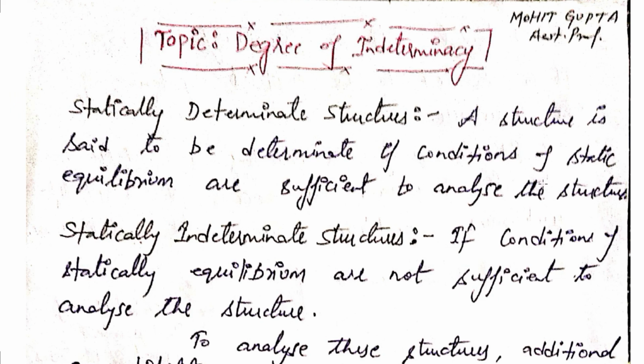We know that in determinate structures, bending moment and shear force are independent of properties of material and cross-sectional area. We also know that in statically determinate structures, no stresses are induced due to temperature changes, and also no stresses are induced due to lack of fit and support settlement. So let's discuss statically indeterminate structures.